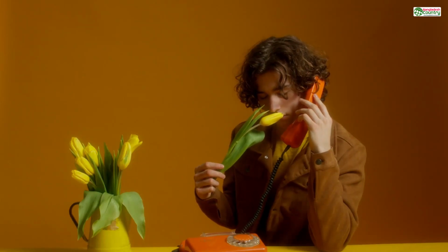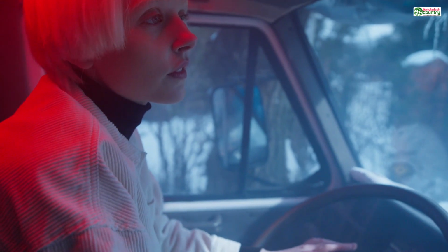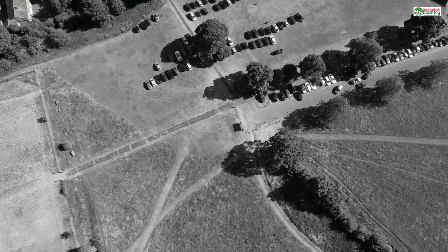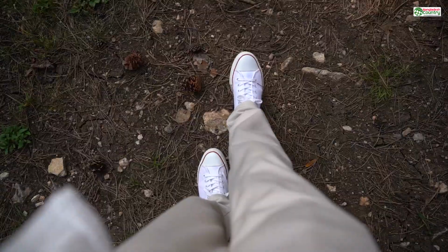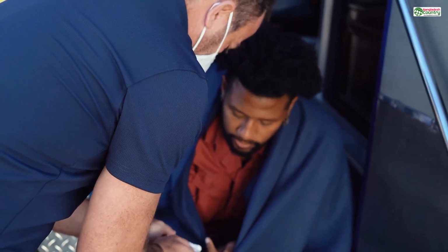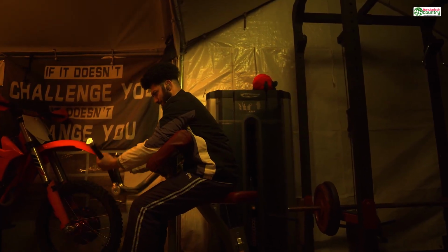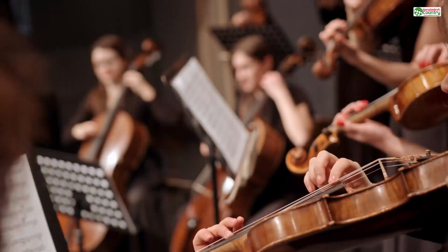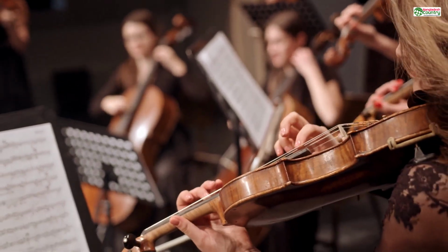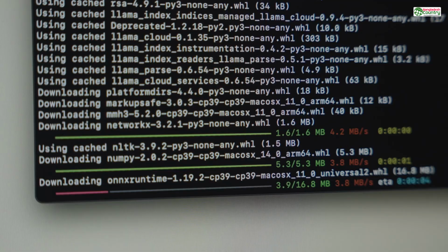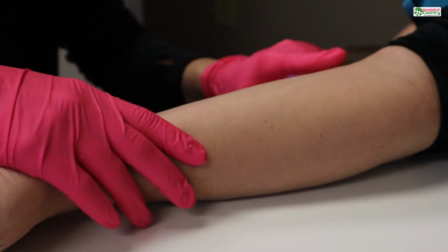Okay, so how do we put this into practice? It all starts inside your design software, before you even create a single polygon. Let's walk through the process. First, you need to tell your software what you're doing. Buried in the settings or preferences of almost every 3D program, whether it's Blender, Fusion 360, ZBrush, or Maya, is a section for scene properties or units. This is your command center for scale. Find it. Your mission is to set 2 things.